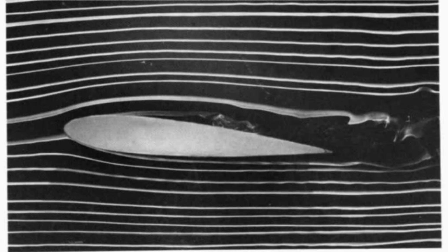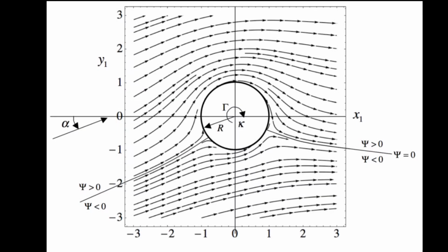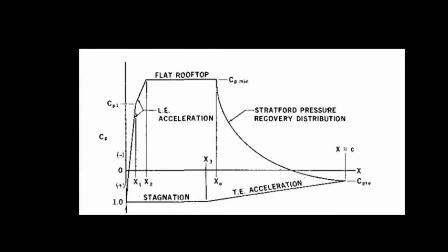This was an important advancement because now wing profiles could be analysed without a wind tunnel and at a substantially reduced cost. Also, it would be unrealistic for the inverse design method, such that without viscous flow there would be no separation and you could generate absurd lift numbers. Going by the previous video about profiles and the Stratford pressure recovery distribution, an airfoil will have a theoretical limit as a result of the flow separation. The aim is to reach the theoretical limits for motorsport, as centre of pressure and moments that a wing has is less important than outright performance.